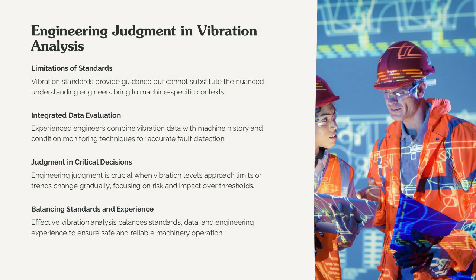Engineering judgment is particularly important when vibration levels fall near standard limits or when trends change gradually. In such cases, decisions should be based on risk, criticality, and operational impact rather than rigid adherence to numerical thresholds. Ultimately, professional vibration analysis balances standards, data, and experience to support safe and reliable machinery operation.